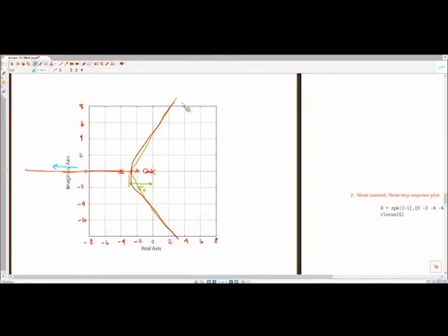In general, we don't have to worry about what's going on with that pole in terms of performance, because we said from previous lectures that as the pole is farther into the left-hand plane, it becomes less and less consequential in terms of the total response. So this one's continuing to move on to the left. It's not going to be a major concern in terms of either stability or performance for us.